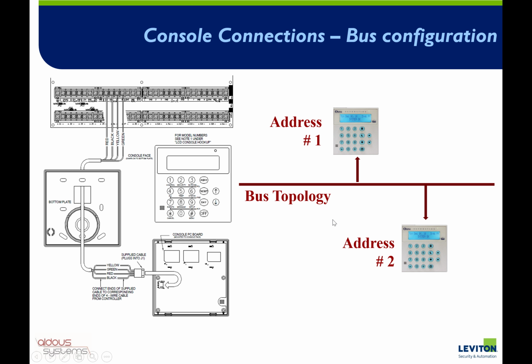Of course, you can have more than one. You can have lots of these keypads if you have multiple entry points that you want to be able to exit and enter from and easily arm and disarm the alarm. Not a problem. Fit one by each door. You may want one in the master bedroom as well for arming the alarm in night mode, but I'd personally rather put a touchscreen in a master bedroom because you can also access cameras and the temperature and lighting as well from the touchscreen, obviously in a more user-friendly format.